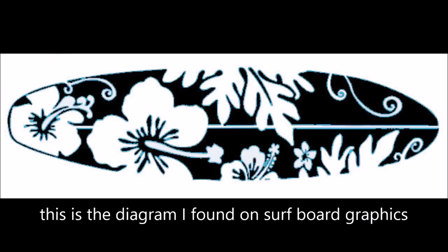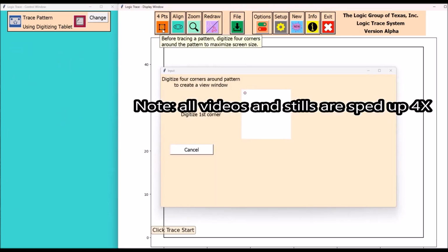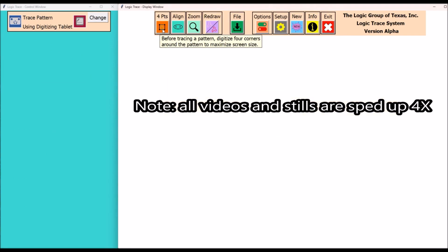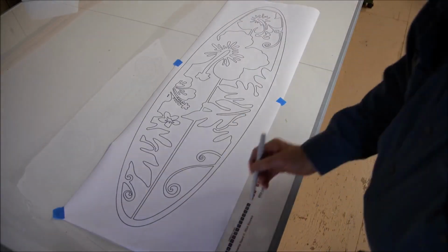Found this picture on the internet of a surfboard graphic. So I downloaded the picture, printed it up, and I'm going to trace it out. First thing here in Logic Trace, we're going to define the four corners of the diagram. And that's just a matter of touching those four corners on the paper diagram.